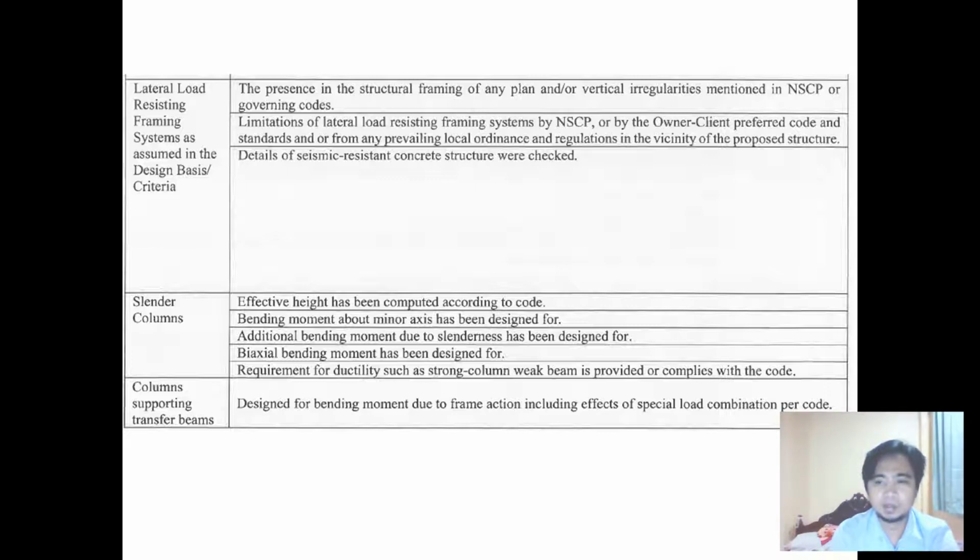capacity of the beam. So usually if a certain column carries a series of beams, like for example, it carries 4 beams or on both axes, what you do is to combine the strength of the two and then transmit it to the column and design the column to resist both beams that are attached to it, so that you will be having a strong columns and weak beams.